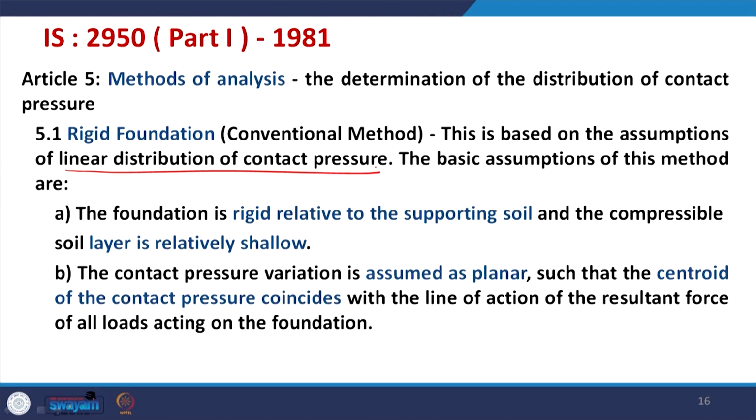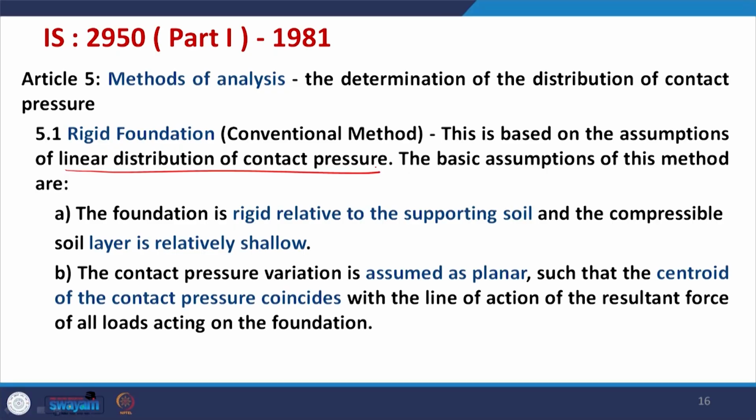Also, the compressible soil layer is relatively shallow, and your soil should be of a little bit good quality, not very bad quality, for using this method.